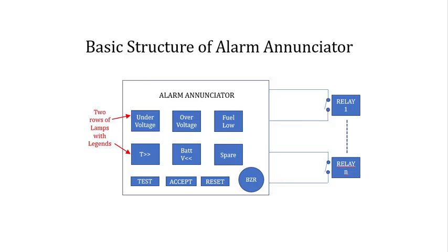Each one of these relays is connected to a lamp through an electronic circuit such that the lamp starts flashing when the corresponding relay contact changes state. This electronic device is called alarm annunciator, which supports several relay contacts. Each lamp on it also provides a label that shows the cause of the problem, as you can see here.